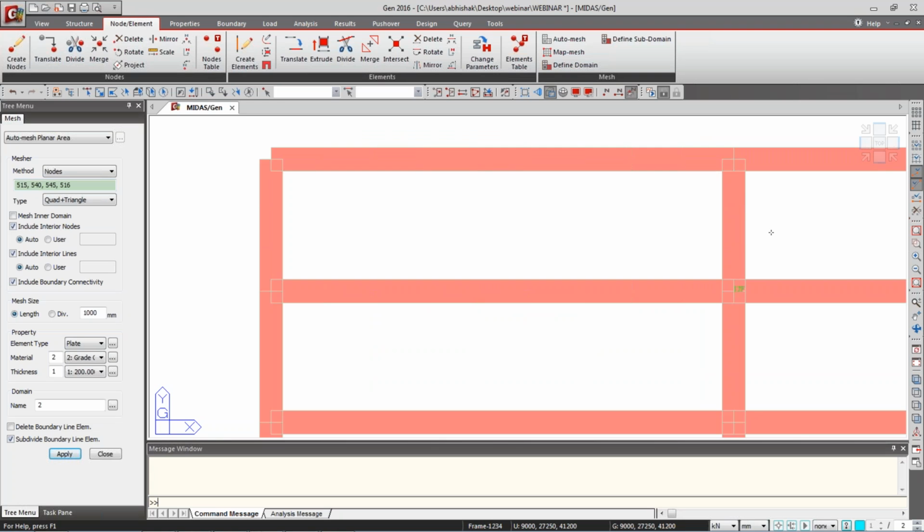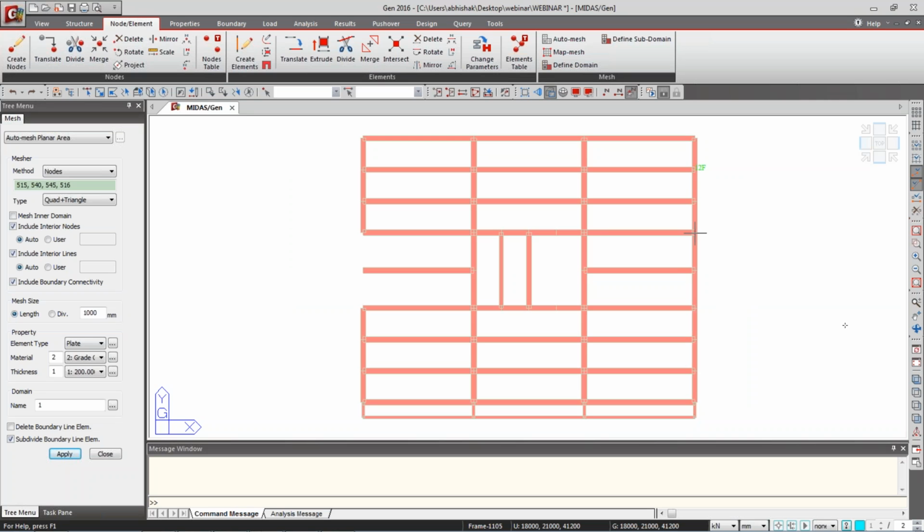So according to that, you have to generate the slab. You can directly take the periphery from the AutoCAD DXF, then select that particular periphery and generate your slab. The second question is how can I import the column. The column also you can import from the AutoCAD DXF. The only thing is you have to generate one line in a 3D direction, meaning in the Z direction.